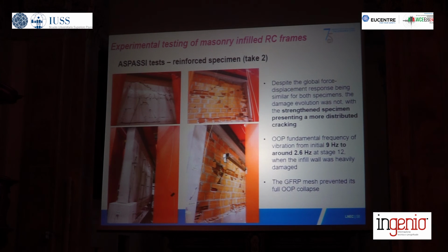So in terms of the damage, you see here the strengthened specimen was presenting a more distributed cracking, much more distributed cracking. In terms of the fundamental frequency on the out-of-plane, we were again going from a large frequency of 9 Hz to around 2.6 Hz at the end, and the reinforcement included in the coating was successful in preventing the full out-of-plane collapse.